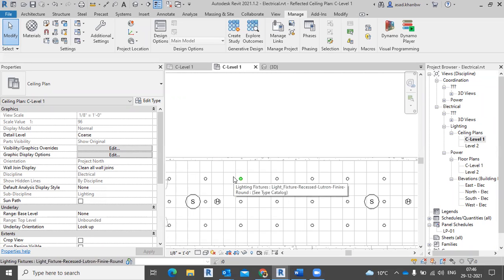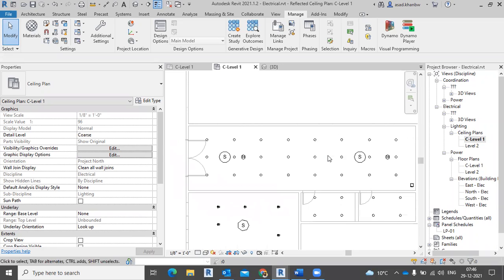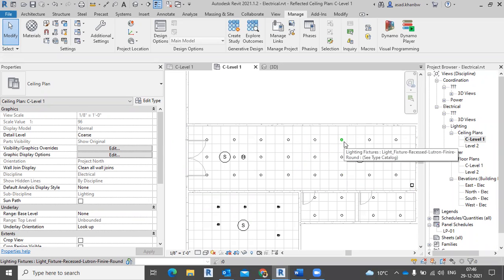Also, if it's a light hazard as per NFPA chapter 13, if you look at this area, you don't have any combustible material. You're not storing anything which can take fire very quickly, like wood, husk, paper, and you're not storing petroleum. It's not a warehouse where you're storing a lot of things, clothes and other things.